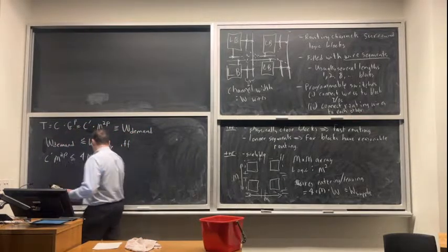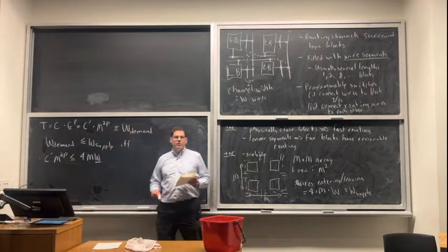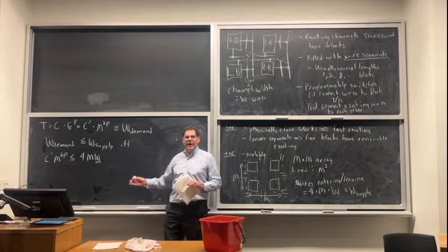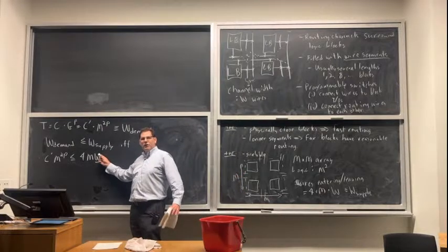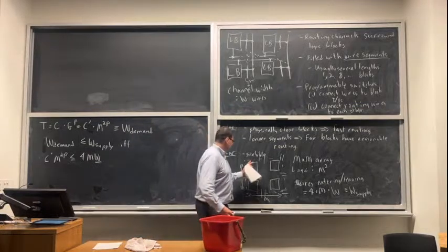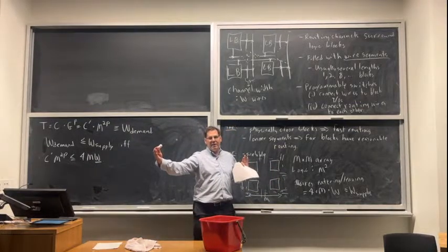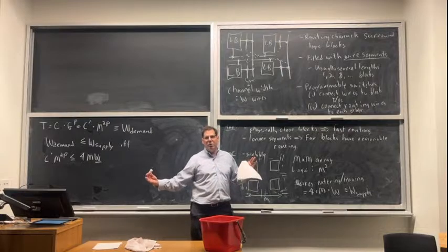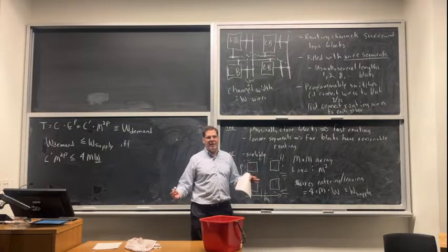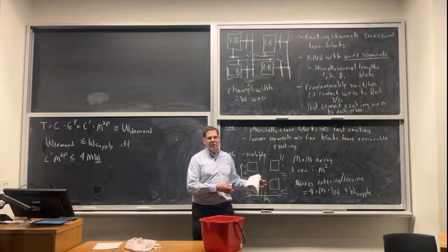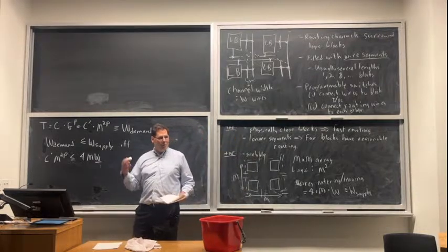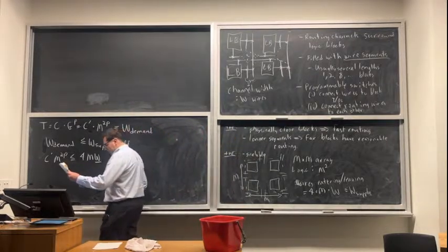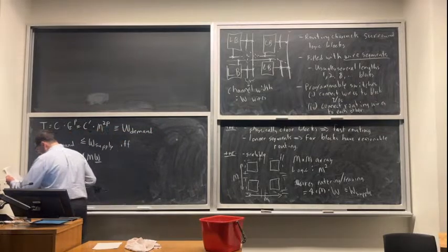So I want to solve for W. That's the number of wires per channel. I care about what happens to that as I make the chip bigger and bigger. I want to know if I need to make my wiring channels really huge, because as I try to scale up this array and make a bigger FPGA, if I have to make the routing channels really wide, it means I'm getting less and less efficient. A larger and larger fraction of my area is actually wiring, and less is logic. But I sell these chips by logic capacity, right? I need to have enough wiring that they work, but I really sell them by capacity. So let's just solve for W.